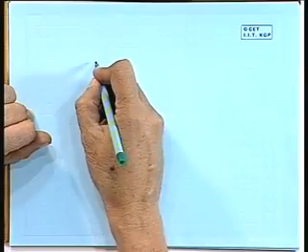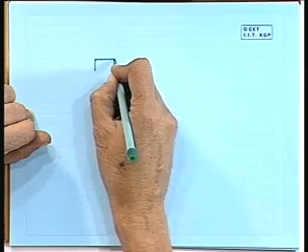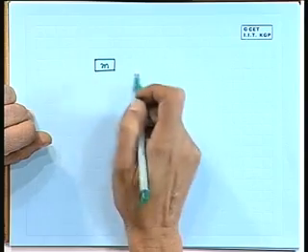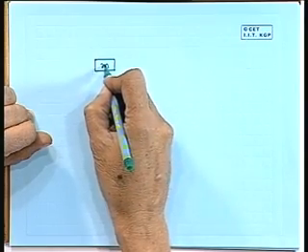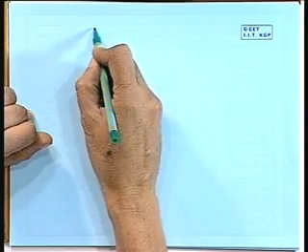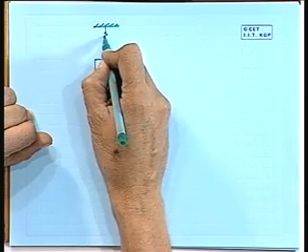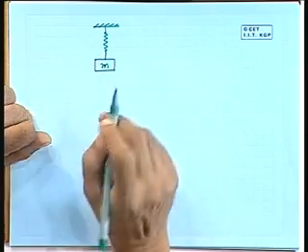Now, the easiest way of mathematical modeling is you consider a mass m concentrated at some point here, and the stiffness of it, the elastic property, is depicted by the spring connected to it. So, you consider a spring, to that you consider a bob, a mass, and that represents my single degree freedom system.